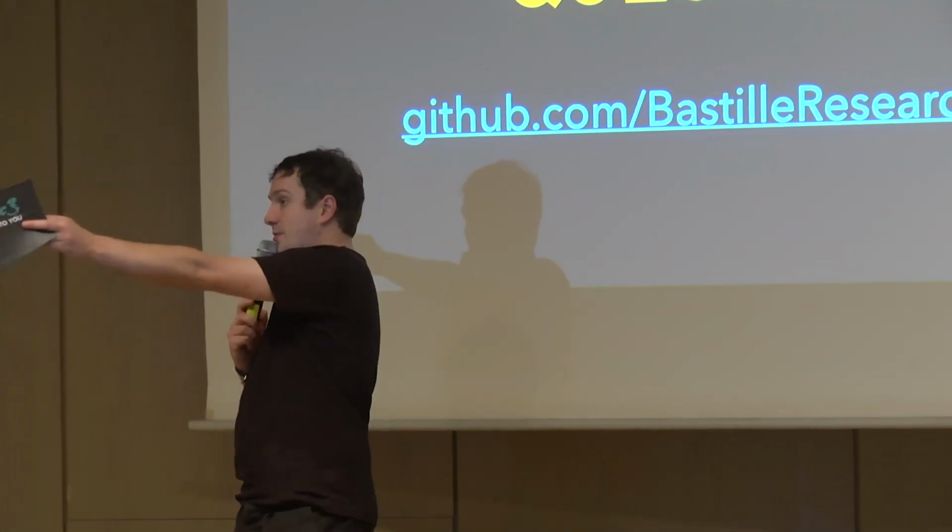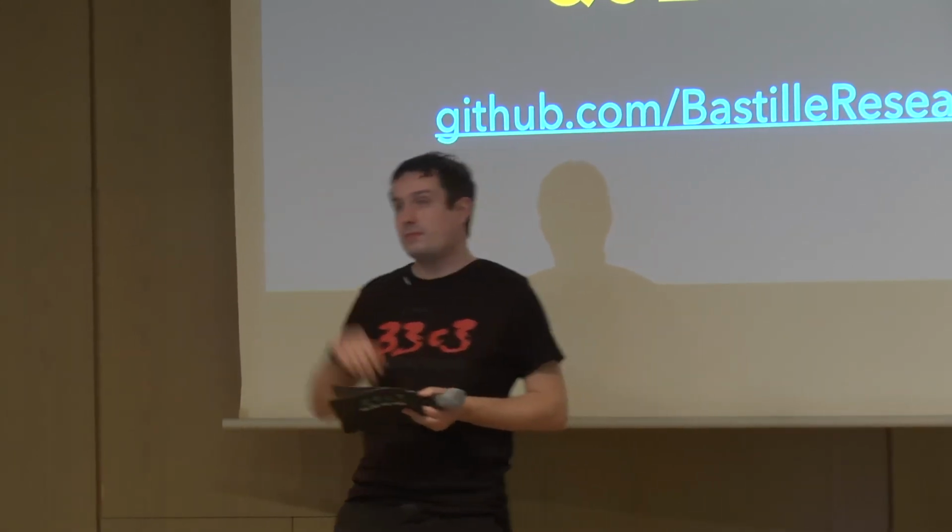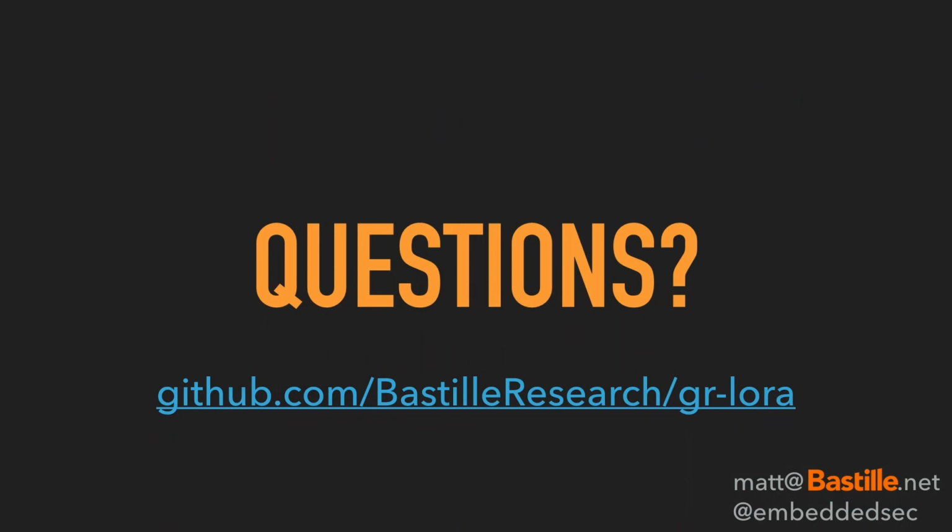Another question from the rear right microphone. So in decoding those two unknown layers, you had your proprietary hardware, and you could send it data, and it won't do the AES and encryption stuff, and it just sends that with its encoding? That's a great question. I kind of skipped over that. The Microchip LoRa radio that I had, this guy right here. I also looked at another one that was a LoRaWAN radio. This is a LoRaWAN radio, but it actually exposes an API to pause the MAC state machine. So you can turn off all of the layer 2 stuff that would add a header and encryption and stuff like that, and send what are close to arbitrary frames. And I say close to arbitrary frames because you can't turn off explicit headers. It's always in the explicit header mode. So this more or less exposed raw payload injection.